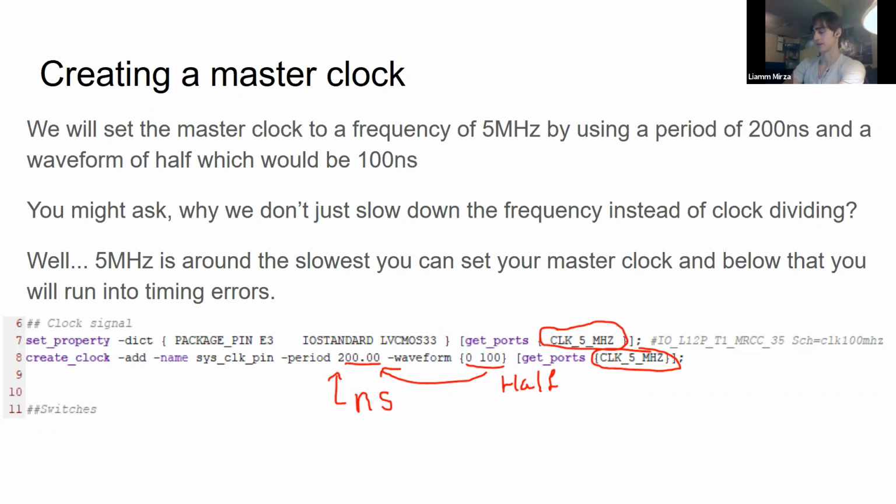We're also using the clock edges, so positive edge, negative edge. So the actual duty cycle isn't as important. As long as it's half, that's good enough. If it's anything besides half, it'll complain. You won't get a synthesis error, you'll get something in implementation and bitstream generation. It'll just say something weird.